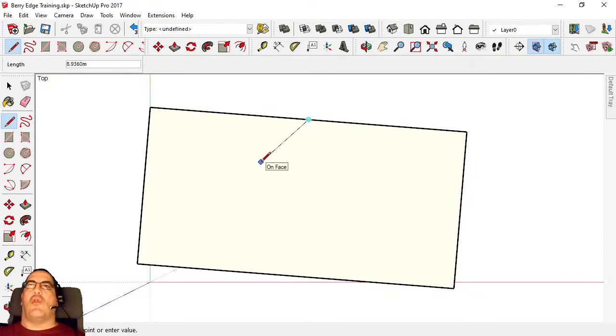With SketchUp, if you move to another face, so let's say for example we want to draw parallel to this face here. If you move to another face, then start moving slowly back away from that face, like if you latch on with a midpoint or a square or something like that and start moving back from that face, you'll see that it will do an automatic construction line for you. And as I move back, there you go, it will actually turn pink to show me when I'm perfectly lined up with that.